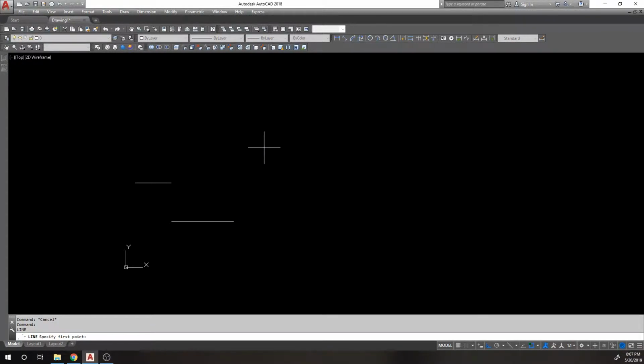Try that again. Put here, .y, click. Okay, now it's asking for an X and a Z. Here's the difference. If I put it right here and left click, no problem. Okay, we're where we want to be. But if I do a .y, select this point, and I happen to have my mouse over here when I click, it's going to place it over there instead. Why does it do this?